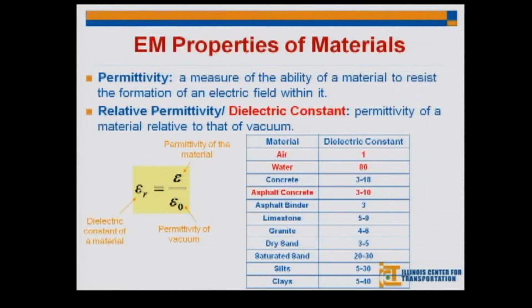Another thing here, if you have free water in the concrete, that will increase the dielectric constant. If the water is attached, then the dielectric constant will be low. So remember here, the water dipole has to move when the electromagnetic waves are applied in order for the dielectric constant to be high.